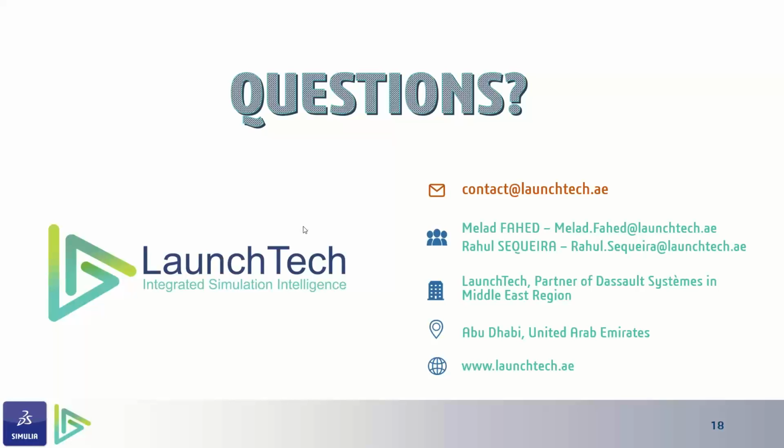There is one more question. Is there a difference if mass is added to projectile nodes or not? I don't know if I understood your question correctly, but if you mean using mass scaling, it would increase the mass of the overall problem and its components, and it would speed up the simulation time. But be careful: when you increase mass, you also cause more kinetic energy to be generated.